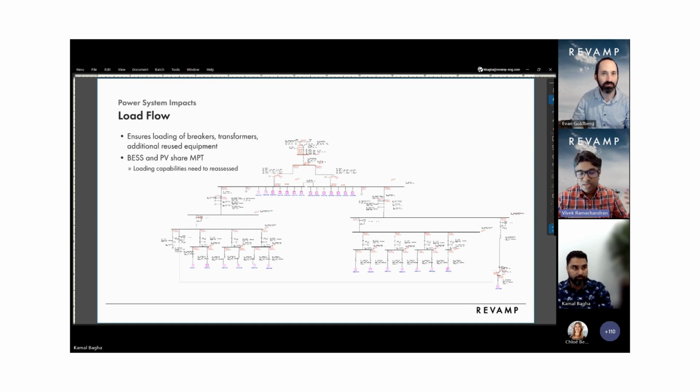So in this case, we have a BESS system coming in that's connected to an existing PV system and sharing some facilities with the system, right? When the PV system is initially designed, if this expansion is not taken into account, a lot of the system sizing is done based on purely the PV system size. A typical example we come across is the main power transformer.